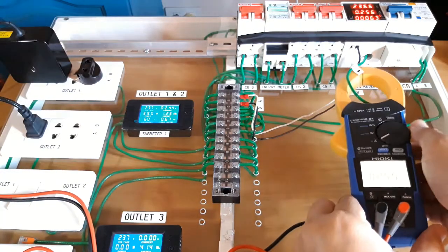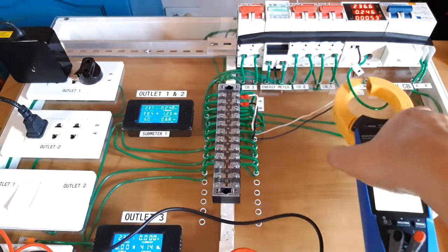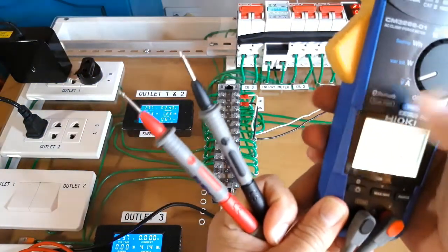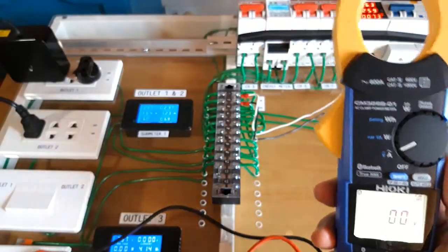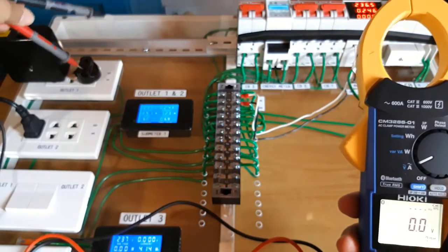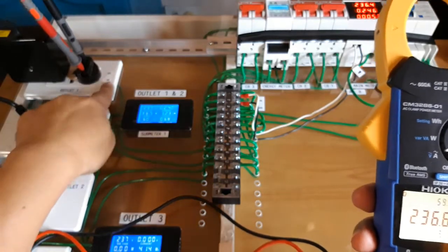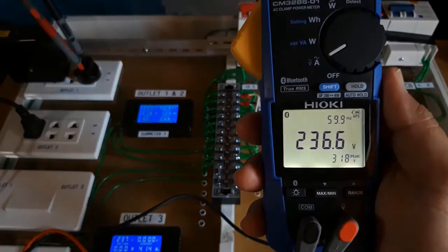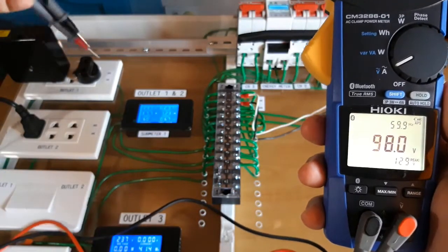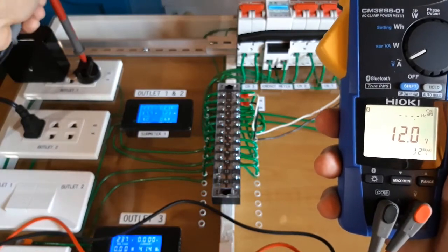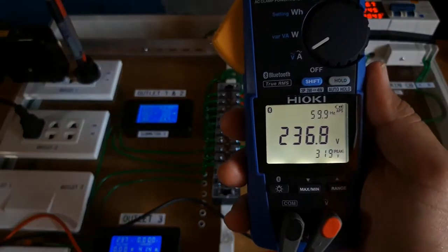Likewise, if I'm measuring voltage only, in this case I'm going to switch the function to voltage, and I'm going to measure here. It wouldn't matter where I point the red probe, whether on line A or line B, and it will measure voltage properly. I can swap them, put the red probe on line B and the black probe on line A, and the voltage is still correctly measured.